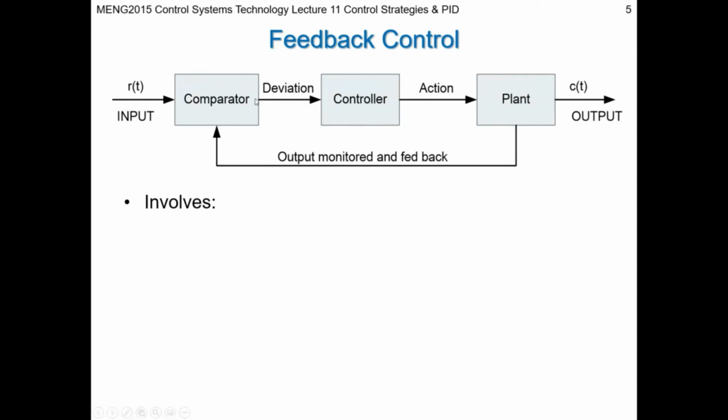It creates an error. That error is then multiplied by a control action or controller algorithm that creates an output action, which is usually sort of a voltage that acts on the servo maybe of the throttle in the engine, if it's a gasoline engine, and then that throttle might be opened or closed based on the perturbation, the error, the nature of the error, whether it's overspeed or underspeed.